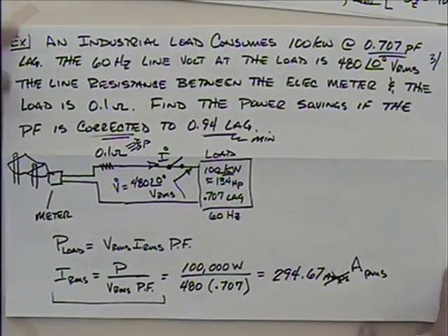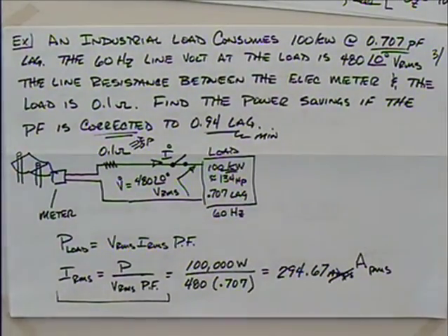You only get those line losses if you're actually running the load. So if you have a house that's sitting vacant and the power meter is turned on, but nothing's running in the house, there should be no power consumed. Now the power company, I think, has a monthly charge whether you use power or not. They're going to get you for that. But there shouldn't be any kilowatt hours consumed.